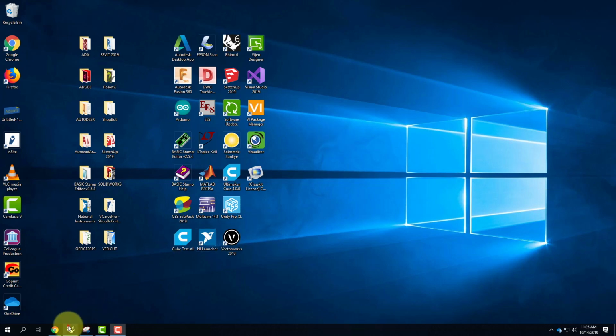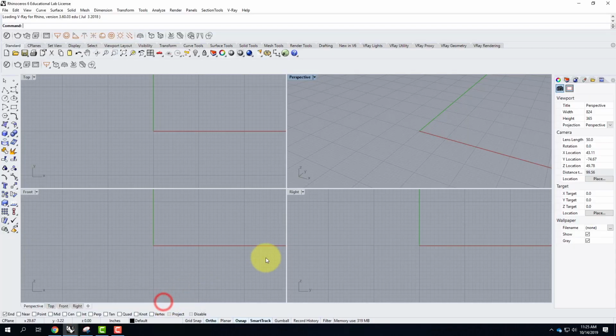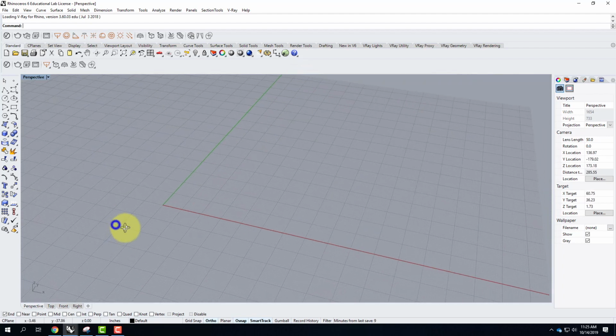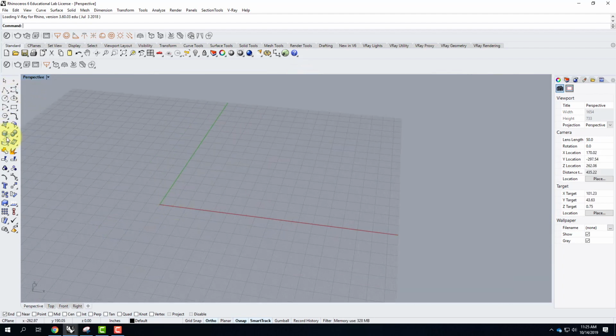So I went ahead and I opened up Rhino. I have a blank large objects inches template set up for myself here. And we're going to start by thinking about how to create these buildings in the first place. So in its most simple sense, we could go into our box corner to corner, start at 0,0, say at 100 feet, comma, 200 feet.